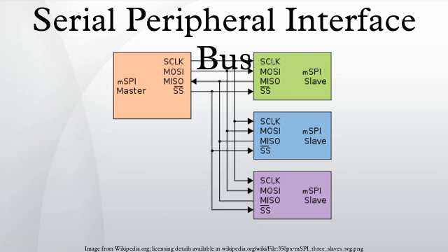SPI master and slave devices may well sample data at different points in that half cycle. This adds more flexibility to the communication channel between the master and slave. Some products use different naming conventions. For example, the TI MSP430 uses the name UCCKPL instead of CPOL, and its UCCKPH is the inverse of CPHA. When connecting two chips together, the clock phase initialization values must be examined to be sure of using the right settings.